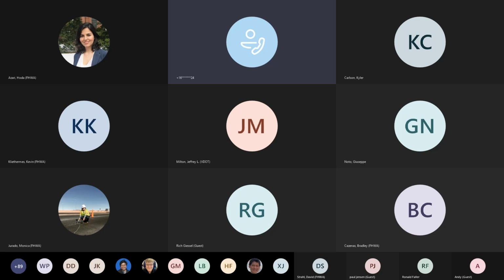We generally recommend an oil-type preservative for durability purposes because that has the best track record at repelling moisture and stabilizing the wood in service. And so it's the most durable treated bridge option. However, in pedestrian applications and more, there's pressure to use waterborne preservatives. These are largely copper-based preservatives. And what that can introduce is some potential corrosion issues between the treated wood and galvanized components.